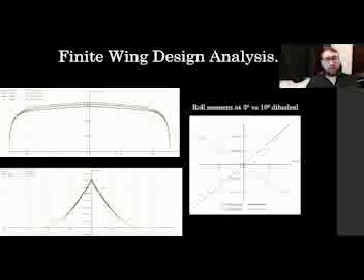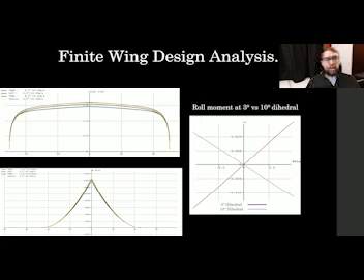The finite design was reproduced in XFLR5 to be analysed with its variety of flow solvers in order to paint a better picture. For example, lifting line theory neglects dihedral in its equations, whereas vortex lattice method considers it, but neglects viscous effects, and therefore does not show any stall behaviour. 3D panel method is also suitable for testing my aerofoil, but it will neglect viscous effects too. The aerodynamic centre was used as the moment reference point and analysis was made.